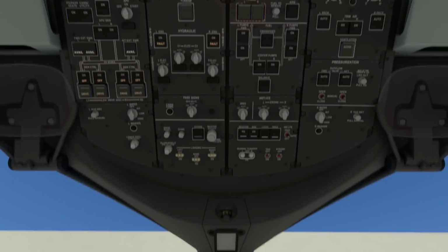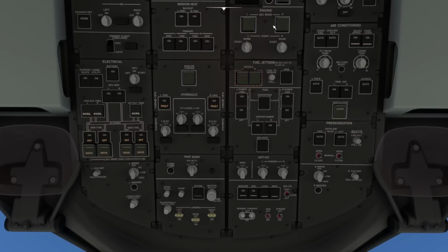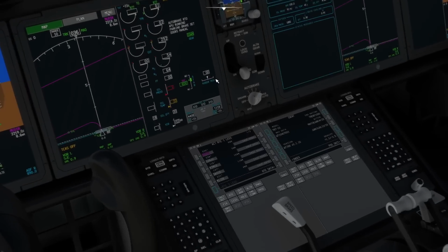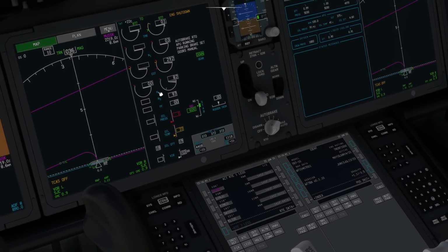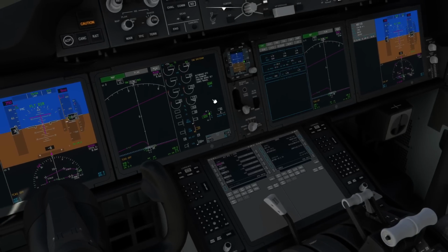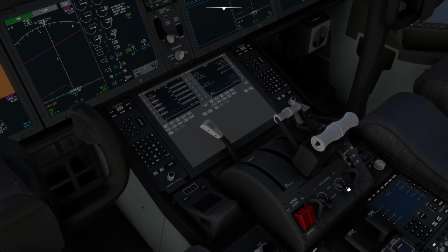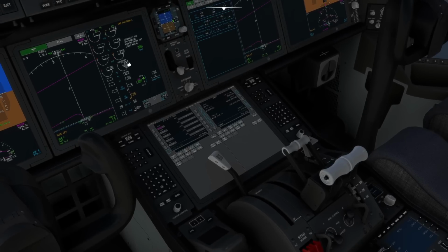So Control 7, the engine starters are up here, way up above us, so we turn the right engine to start. If we look down in the cockpit at the engine management screen here, you can see the N2 number, the gas turbine number, is coming up. This is a percentage of its speed, so when it gets to 20%, we can advance the fuel control lever for the right engine. So 18, 19 and 20, advance the right lever, and you can see auto start is happening, the exhaust gas temperature should start rising, and the turbofan will accelerate as well.